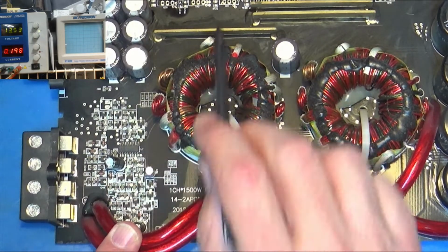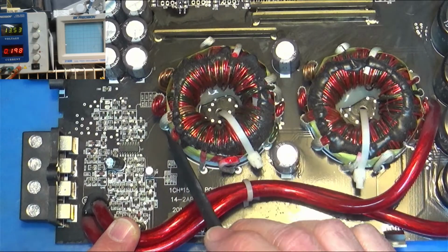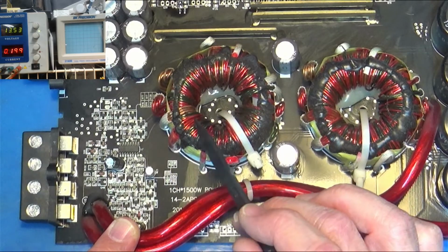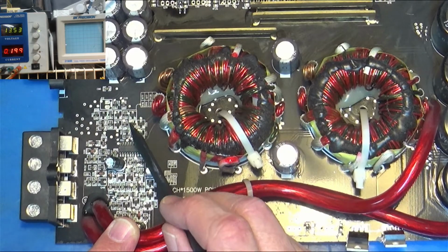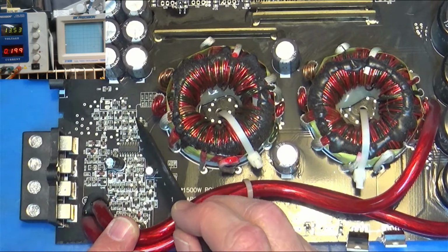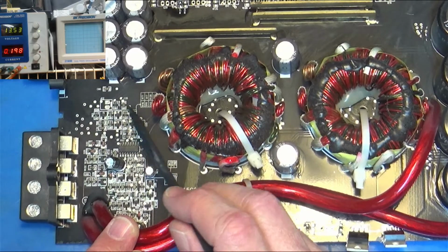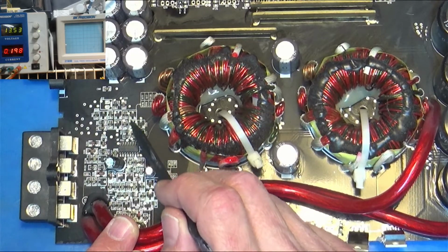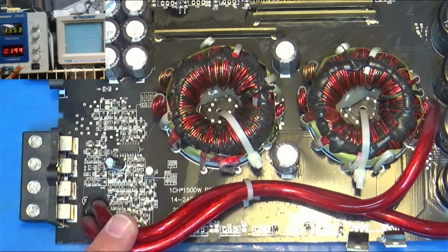the outputs. And anytime you have damage like we had up here, where the gate resistors and stuff totally fried, it normally comes back and at least wipes out the PNP transistors on one of these pull-up, pull-downs. Now, I have a video where I draw all of the schematic out, and I tell you how, when you have these out, you can meter from positive and negative to ground, and figure out which is the PNP and which is the NPN.